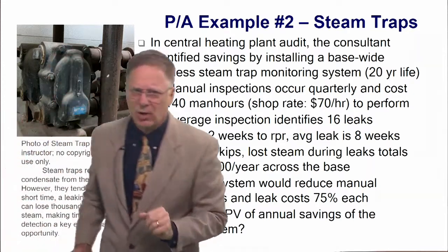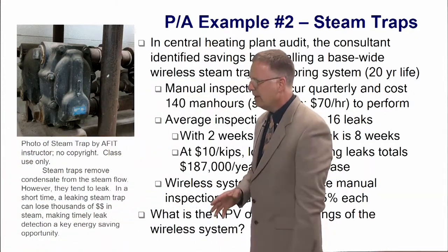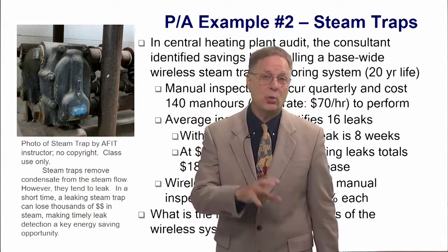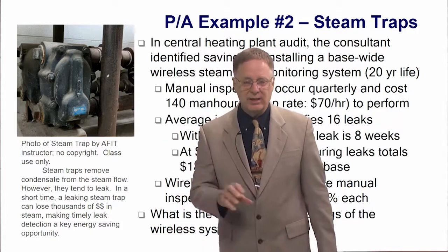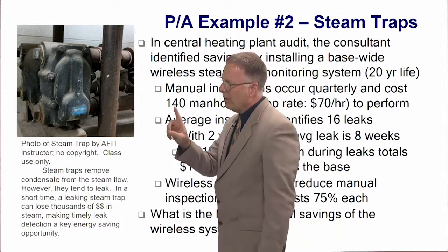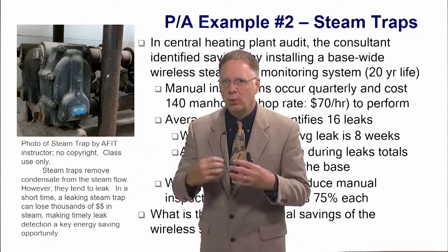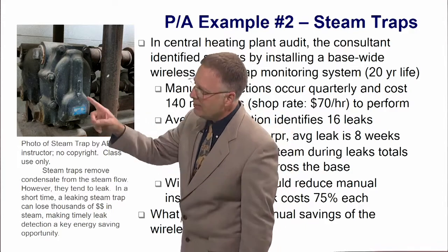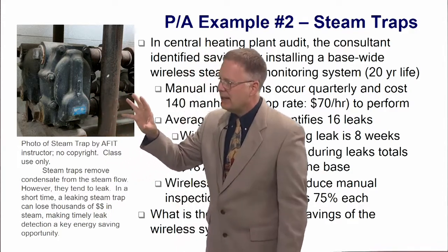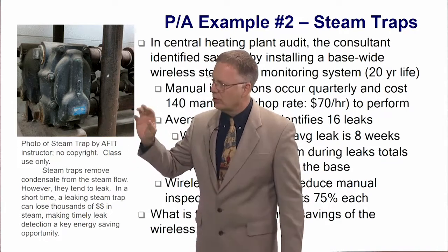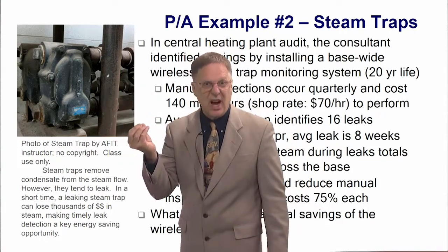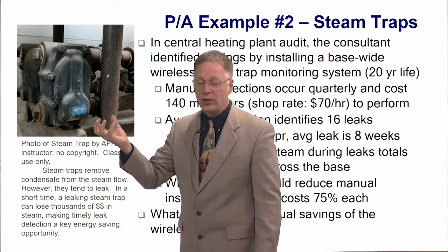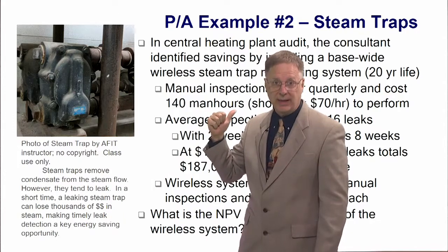Now let me explain what steam traps are so you can kind of get what the idea here is. If you've got a centralized heating system on the base where they got steam or high pressure water or whatever it is, that's going around on the base, if you've got steam, what they have to have at every single location where you pull the steam out of that central system, every single location, you've got a steam trap. And what that steam trap does is as the water cools and as the steam cools, it will have a condensate. And this steam trap collects that condensate at the location and sends it back to the steam plant.